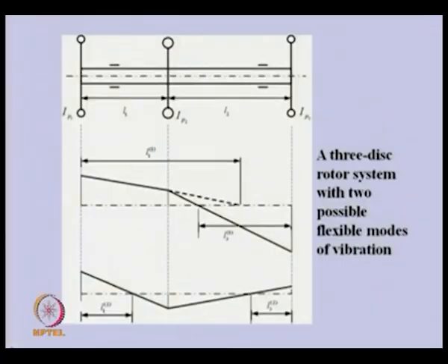this can be obtained. So, this is the 3 rotor system. We are interested in obtaining the torsional natural frequency of this, because the supports are essentially free with respect to torsional vibration. In this case we expect that one natural frequency will be 0, because with free vibration boundary conditions, one of the natural frequencies is 0, and the corresponding mode shape is what we call a rigid body mode, in which all the disks have the same displacement.